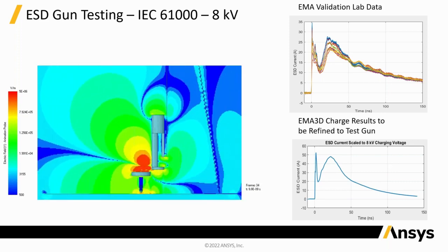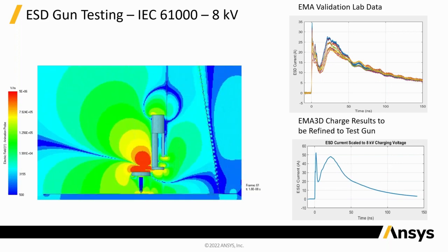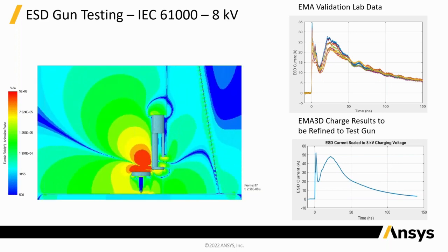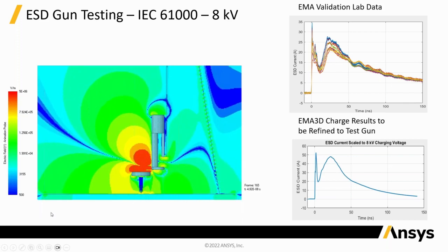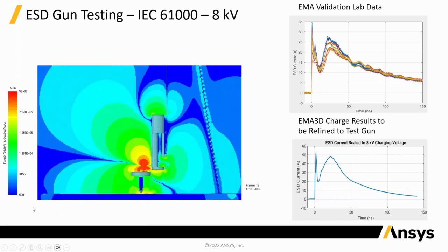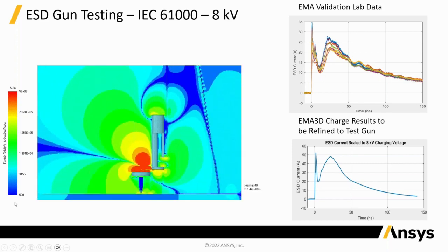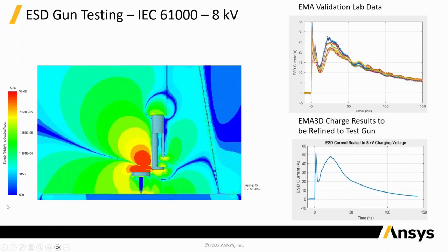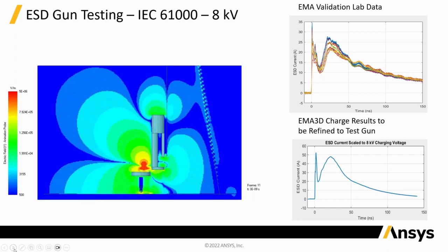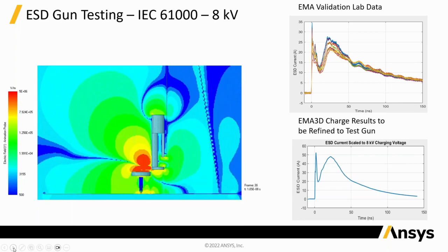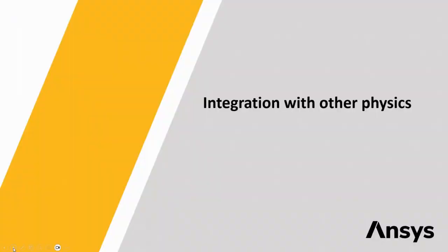So this type of simulation previously wasn't really available, but you have your input. You do need to understand the air properties you're working with because it matters greatly. We've seen some modeling where additional things like salt brine have caused a change in conductivity and made an arc possible where they didn't think it would be possible. So it depends very greatly on the environment that you're doing this in. But this is another type of simulation that's available.